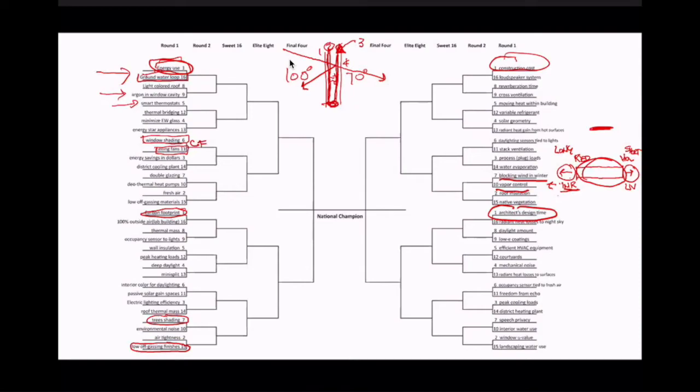And so what's happening in a ventilated attic, here's our building, we'll put the radiant barrier here often. The sun is beating down on the roof, especially if it's black, and that roof may be 200 degrees. So the underside of that roof may be 170 degrees. So you have a 70-degree ceiling in view of a 170-degree underside of the roof.